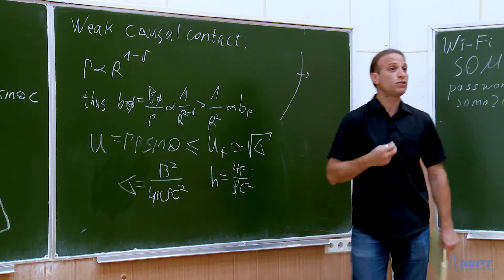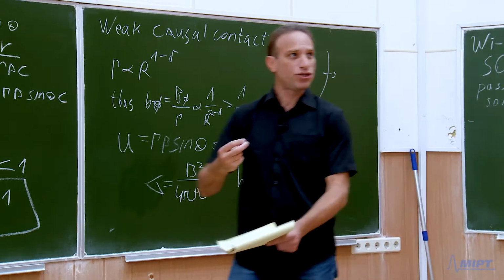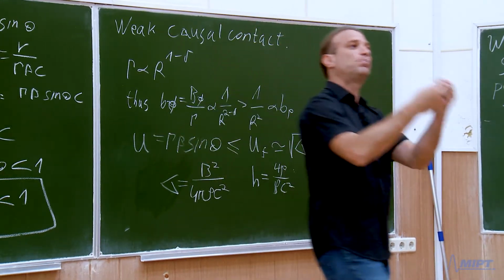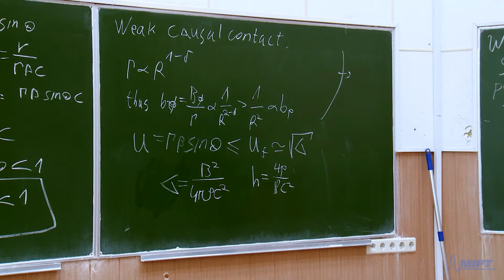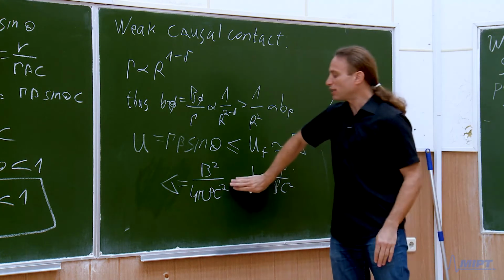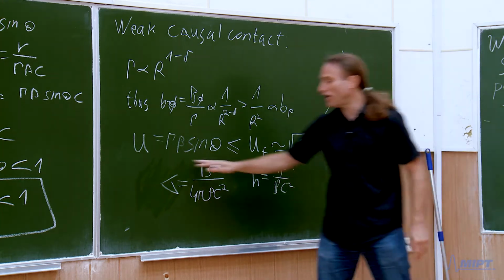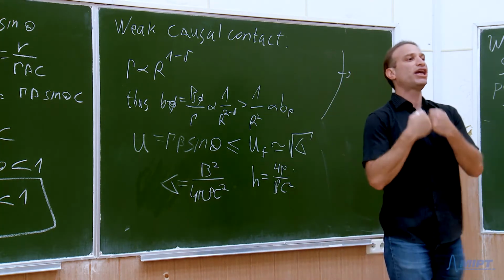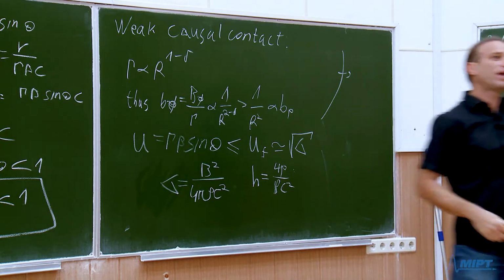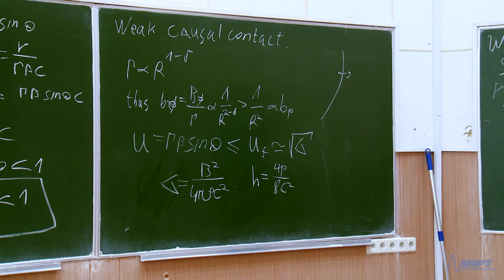The importance of this quantity is that it tells you how much energy I can eventually disperse to each mass unit if I want to accelerate the flow. So the initial value of sigma tells me how much energy I have in my bank, and this energy I can theoretically eventually put into the flow as bulk motion. Okay, this is my bank.